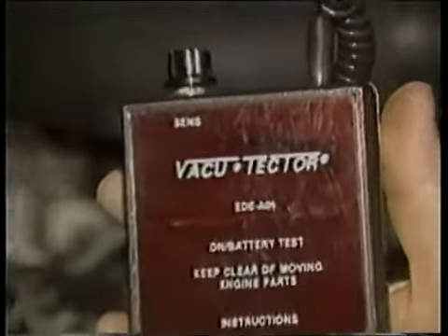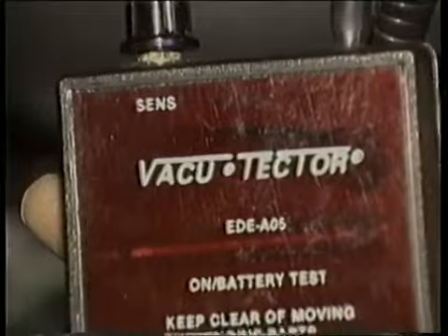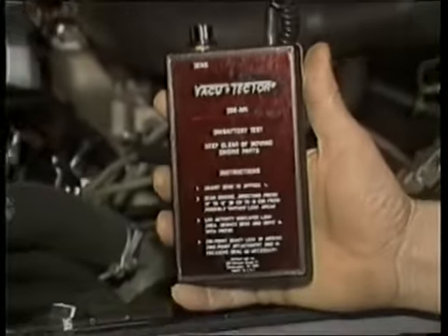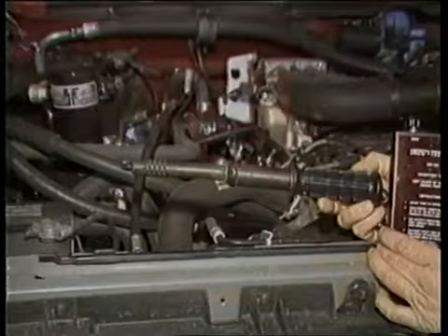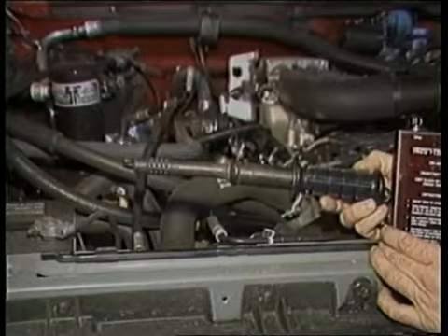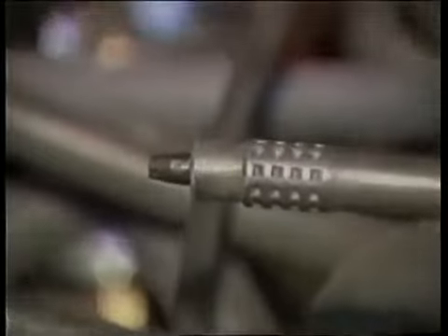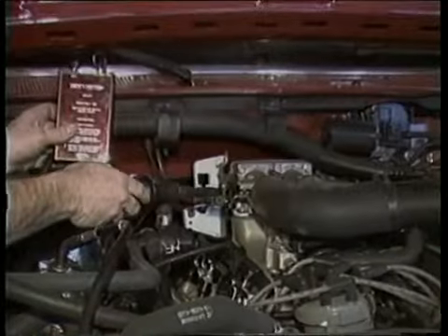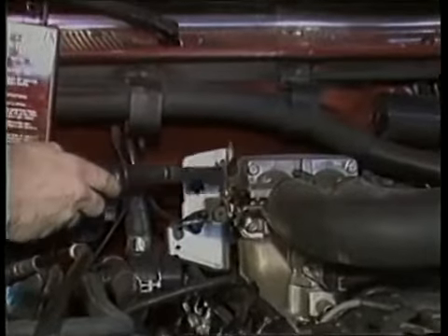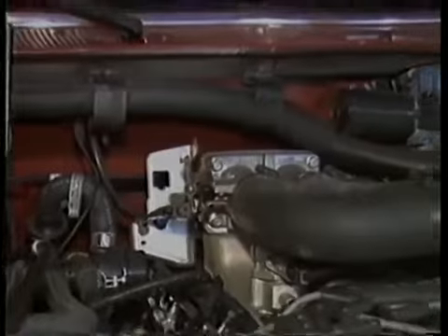Move the tube around any hoses, gaskets, or fittings that might be leaking and making a hissing sound. A vacuum leak detector is a handy tool that works even better than a conventional stethoscope. It uses electronic circuitry and a special test prod to amplify any sounds coming from around the engine and vacuum lines. By moving the prod around potential sources of leaks, it will amplify and allow you to locate leaks more quickly and accurately.